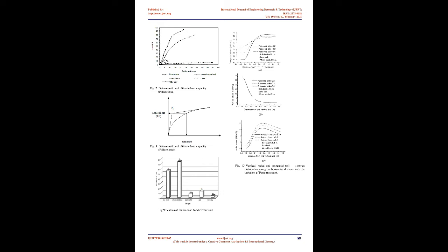To solve these models, there are 3 computer programs using MATLAB software. The first software is designed to get time domain road input, and figure 5 displays the road input history for the front wheels, while the road under the rear wheels shifts like equation 10. The parameters for the road formula are 15 Hz frequency and 5*10^-6 road roughness.